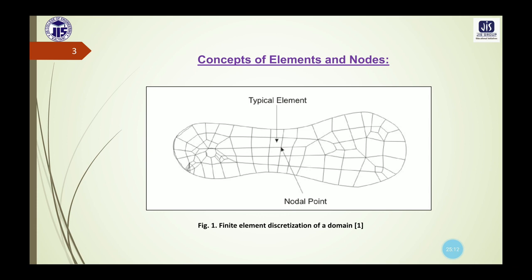Now, each of these elements contains the material and geometrical properties of the total structure. The material properties inside an element are assumed to be constant. Such elements may be one-dimensional, two-dimensional or three-dimensional elements. The physical object can be modeled by choosing appropriate elements such as the frame element, shell, solid element or plate element, etc. After this modeling, all the elements can be assembled to obtain the solution of the entire domain or structure under certain loading conditions.